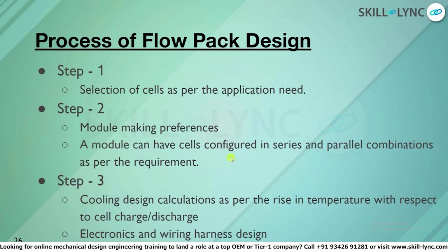The most important factor for this whole pack is the cooling design. Now we have modules in place, we have cell configuration in place. These cells are for high capacity, high voltage applications, so they dissipate a lot of heat because a lot of charging and discharging happens. With such an amount of heat being generated, it's very important to extract the heat. Therefore, the cooling design calculations have to be intact.